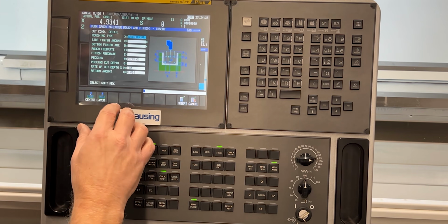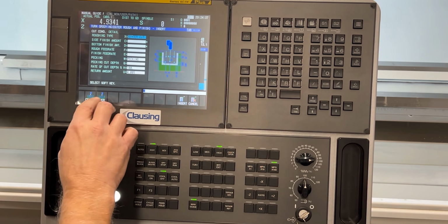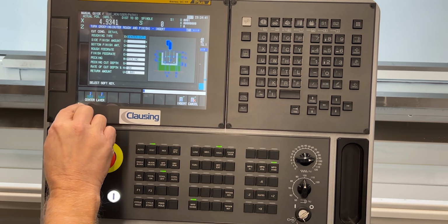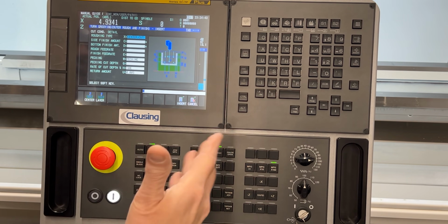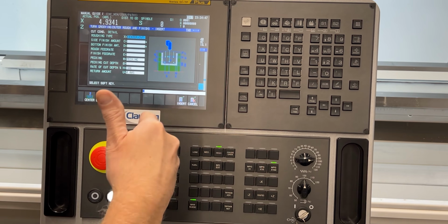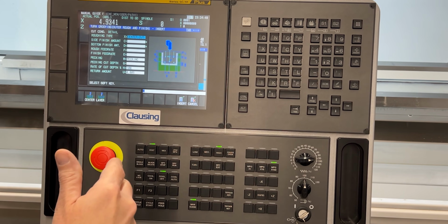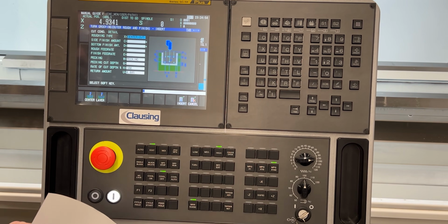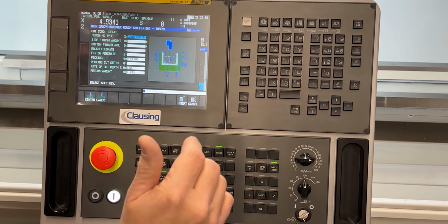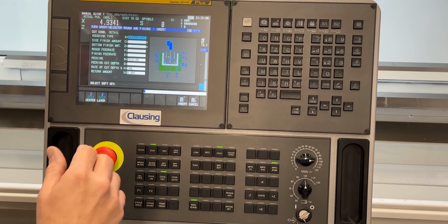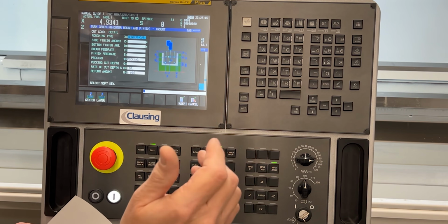And I'm going to start filling in the information. We've got center cut, the first thing, or layer. Center will come to the center of the groove, and if I have a pecking cycle active, it will peck down at the center, come back out, step over, and start opening up and widen the groove. Layer will go into the first peck depth each time along the same diameter, so it'll open up the groove at the first peck depth.